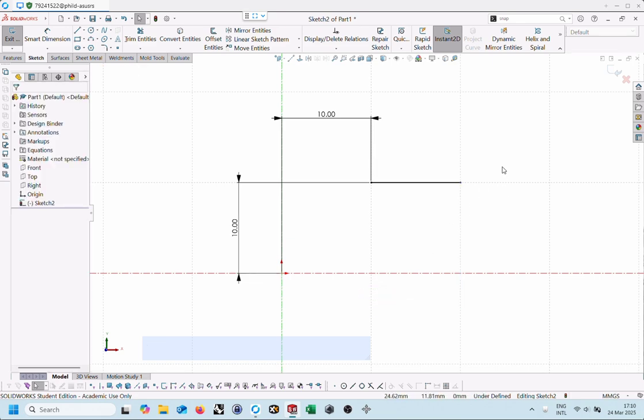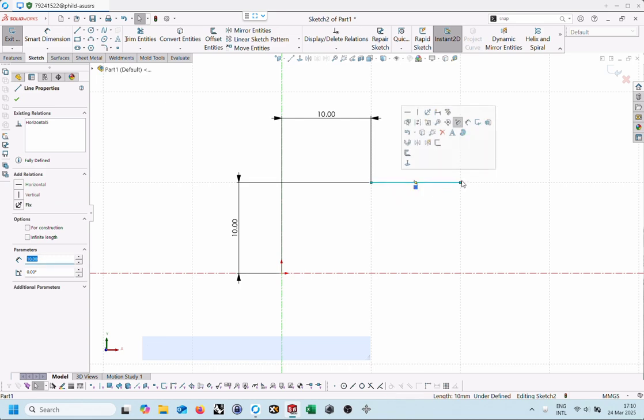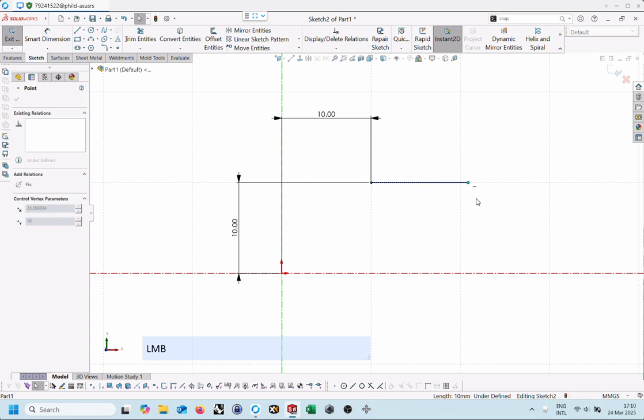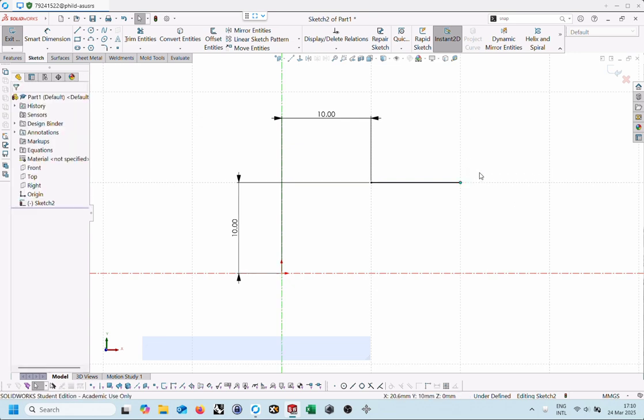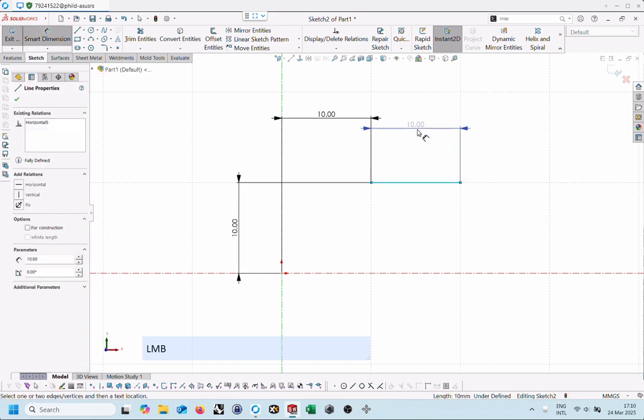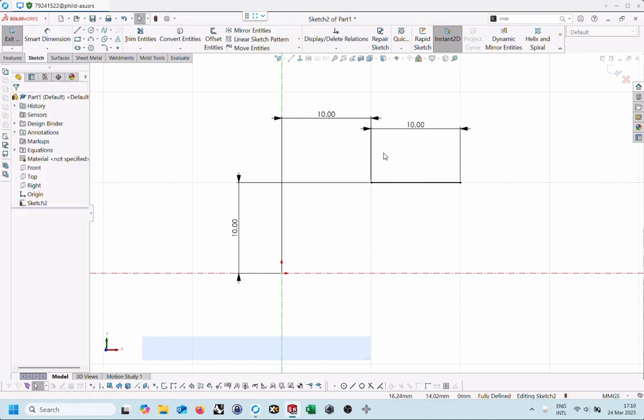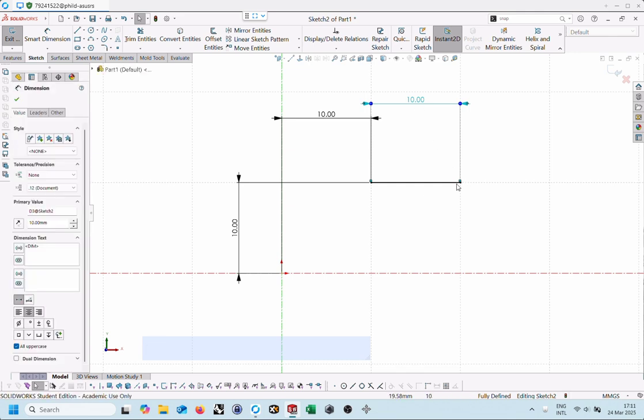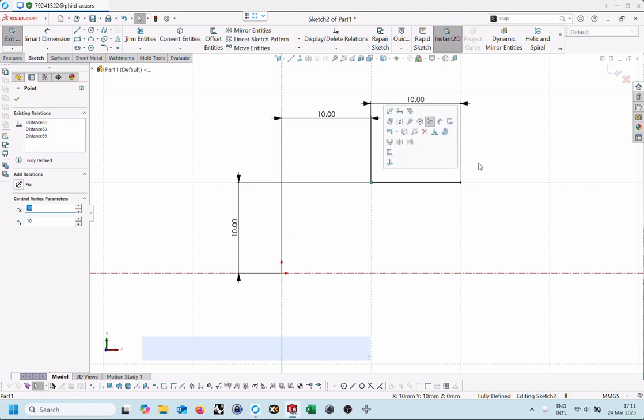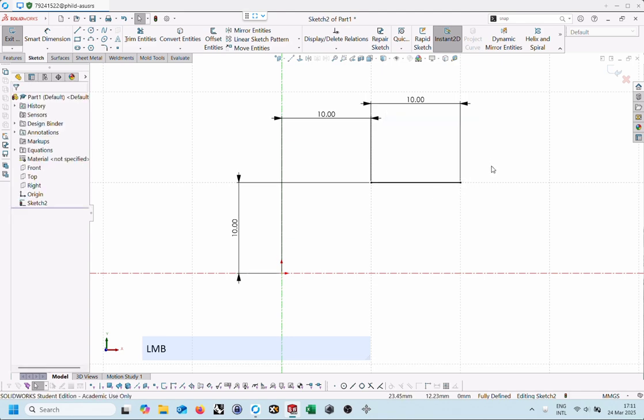We really want to know if we start from that position at 10 and 10 and we go along a horizontal direction. So I can drag this out, but I cannot drag it up or down. Control Z. 10 millimeters. That is the line. The line is positioned at 10 and 10, and then you can go along another further 10 millimeters to get to its end point. So its start point is at 10, 10, and its end point is another 10 millimeters in the horizontal direction.